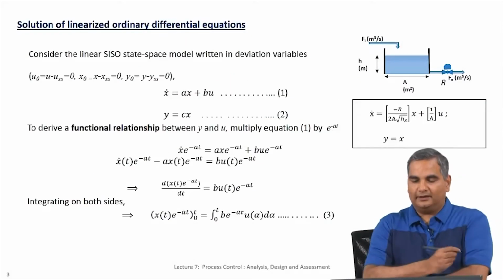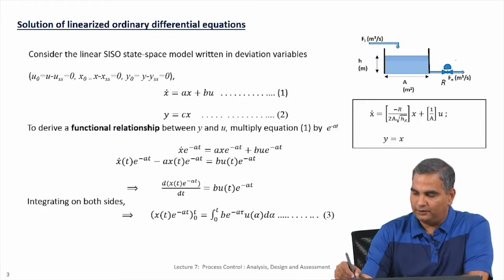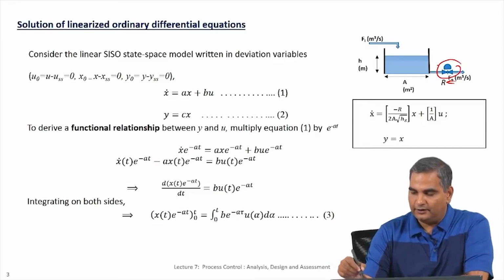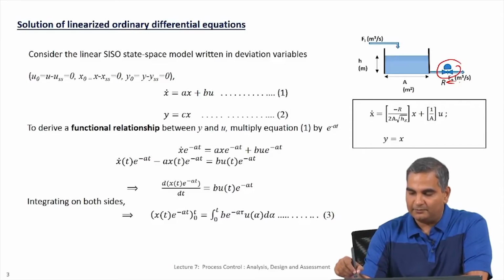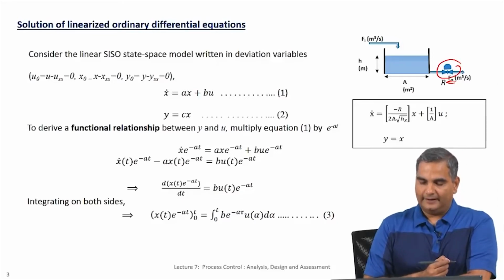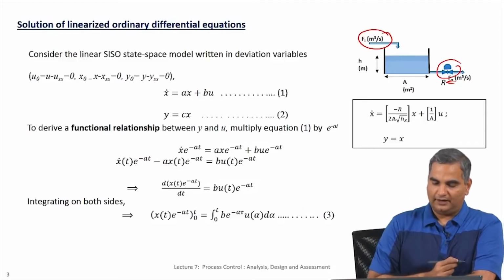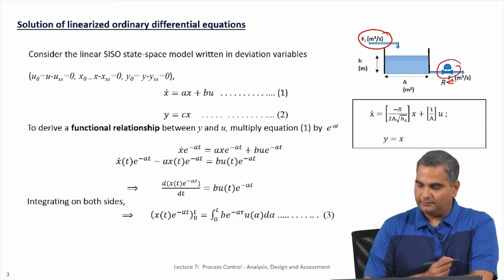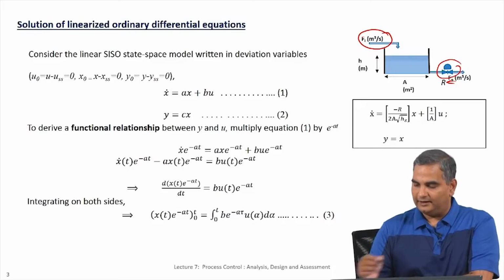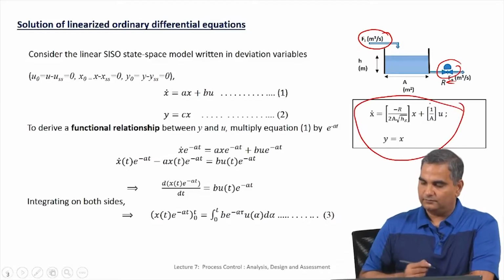Now, let us go back to the state space form that we have, and though I put in a valve here, this is to introduce the notion of R and not really to finish a control diagram. So, now if I have a tank like this and I am going to manipulate this with a control valve, I have this as my Fi, then we derive this equation which is of this form.